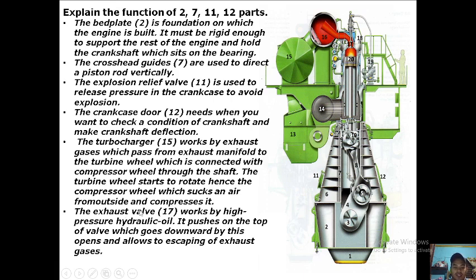Number 17 is the exhaust valve. It works by high pressure hydraulic oil, so it pushes on the top of the valve which goes downward. By this it opens and allows the escaping of exhaust gases.